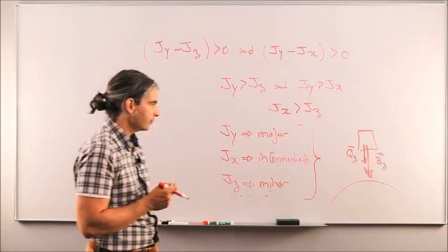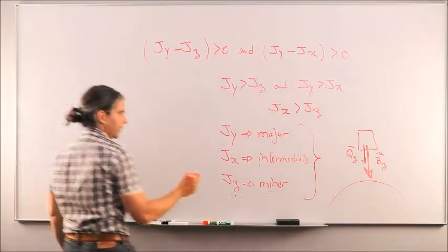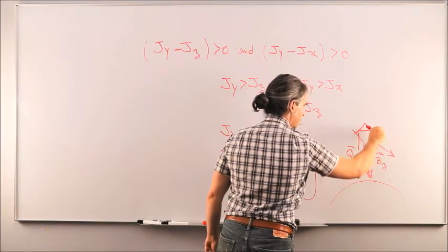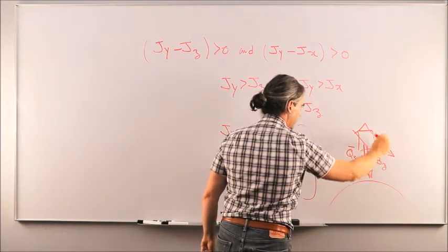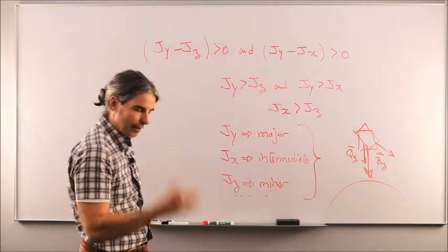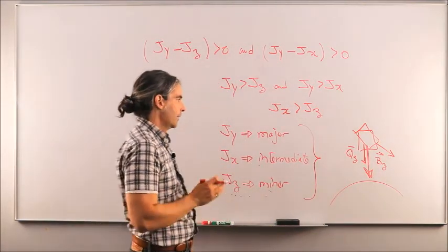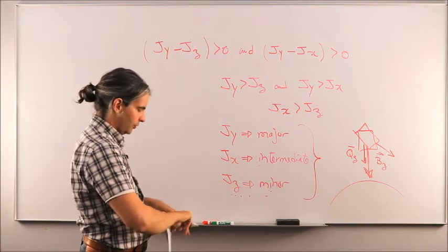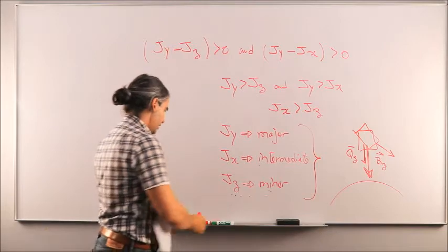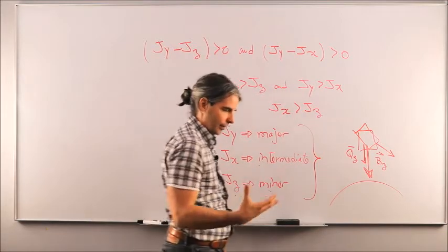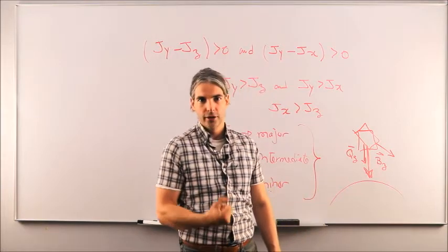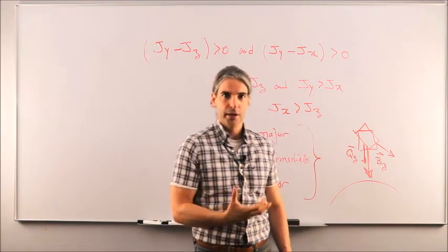Okay? Doing so, should the spacecraft ever deviate slightly from the ideal orientation, well, gravity gradient will put it right back in, right back down, okay? Now, there's a couple of things you can do to enhance this effect, such that gravity gradient has a larger torque in terms of restoring torque on the spacecraft itself.